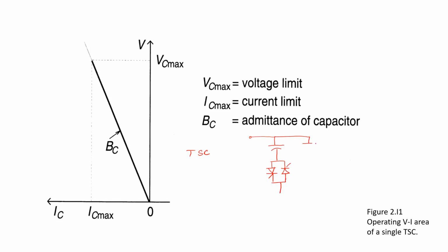Similarly, the second capacitor is there, and this is C1, this is C2, and again there are thyristor valves. Either individual limiting reactors are there. Okay, so by using different combinations, no doubt we can use different values of capacitor, and we can go in steps to control the VAR generation in the transmission line.